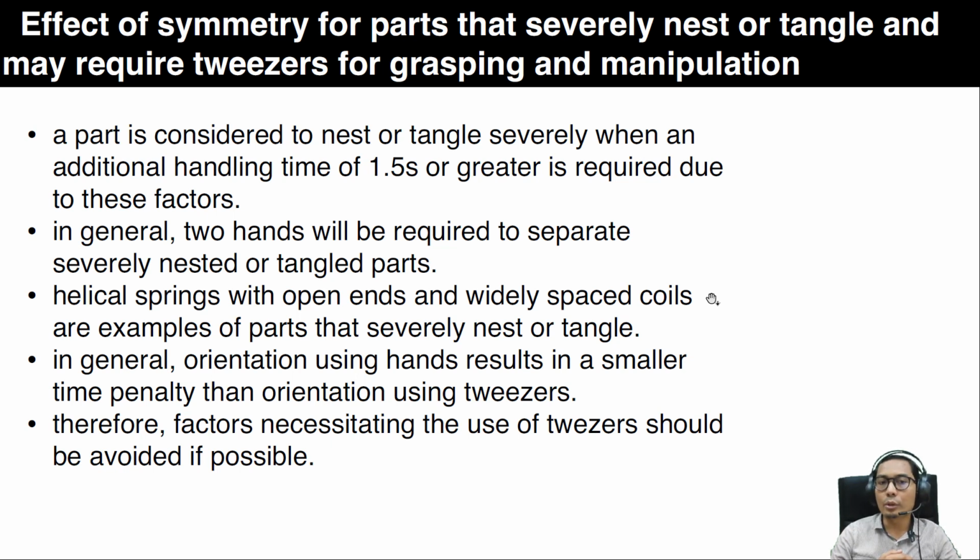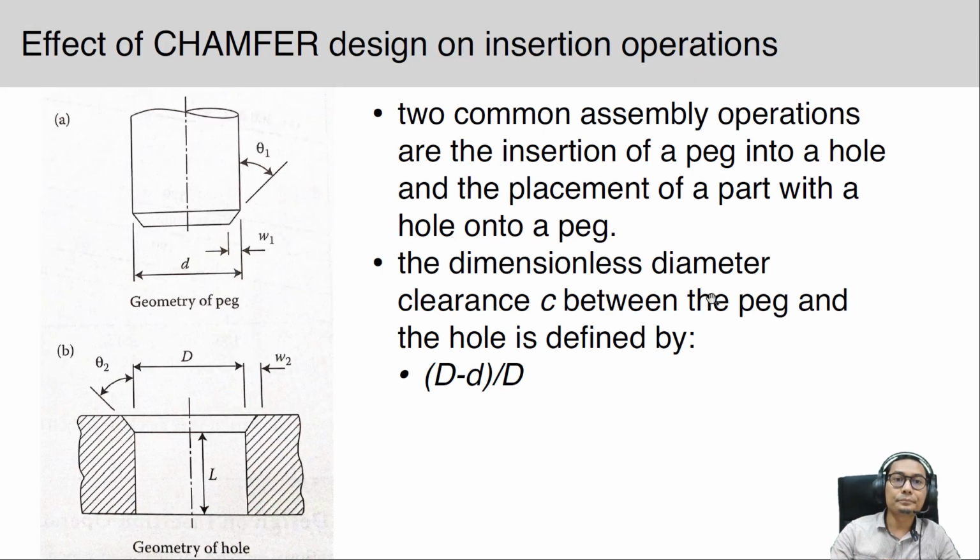So in general, orientation using hands results in a smaller time penalty than orientation using tweezers. Therefore, factors necessitating the use of tweezers should be avoided if possible. Okay, now we will see the effect of chamfer design on insertion operations.